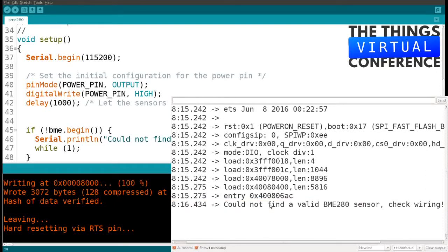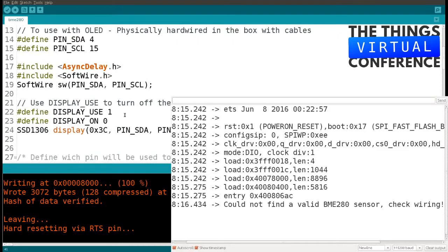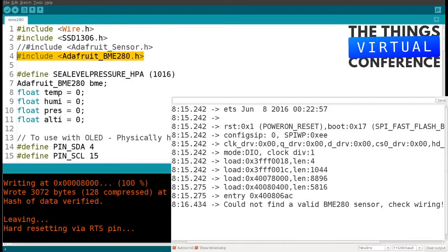Check wiring. Oh, yeah. And that's where we come to the very interesting point. The I2C sensors, like the one wire bus, the I2C sensors, they have numbers, they have IDs, and if you use the Adafruit library, they are not defined inside your program. They are defined inside this file. So I have now to find this file and check that I have the right ID inside this library before I can flash it again and see if it works. It's normally that problem.